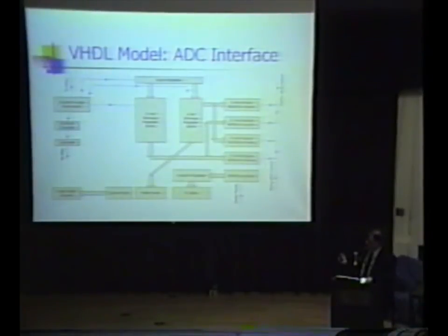This interface is also used as the main communication component between all the other VHDL components in the system. As you can see here, there are a couple of output muxes to the filter and the mixing communication areas, and some filter communication right here. And this is also the component that outputs to the digital to analog converter.